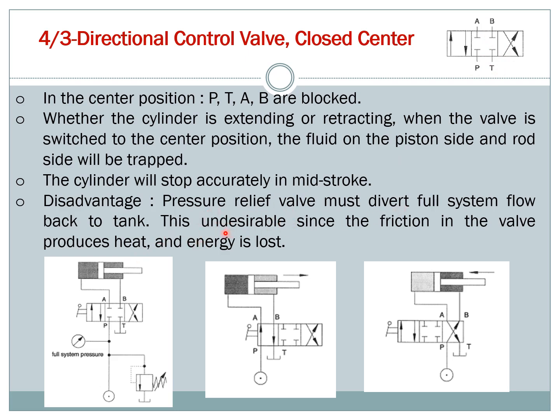You don't prefer this because hydraulics uses oil, so it can cause friction, and the friction will make the oil become hot, and you will have energy loss.